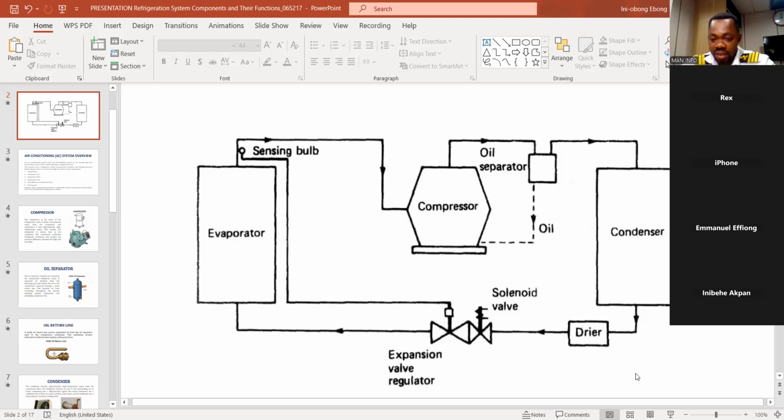So to check your compressor, based on the question Daniel asked, you need to select your multimeter to resistance and use that to check if the compressor is short circuiting. From the three terminals, you touch across them to check continuity. If there is continuity, then the compressor is good. At that point of continuity, you should also see your resistance reading. But if you check and either of the terminals does not beep, meaning that the compressor is short. That's that on an HVAC compressor.